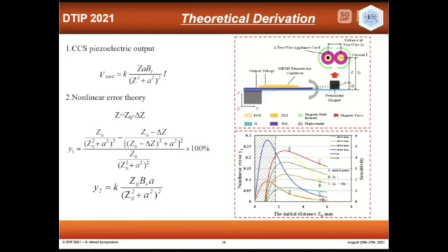The black line is the rated current of the wire, which means that the curve on the right side of the black line is valid. It can be found that the nonlinear error decreases with the increase of Z0, but so does the sensitivity. In this case, increasing the magnetic induction intensity can make up for the decrease of the sensitivity.